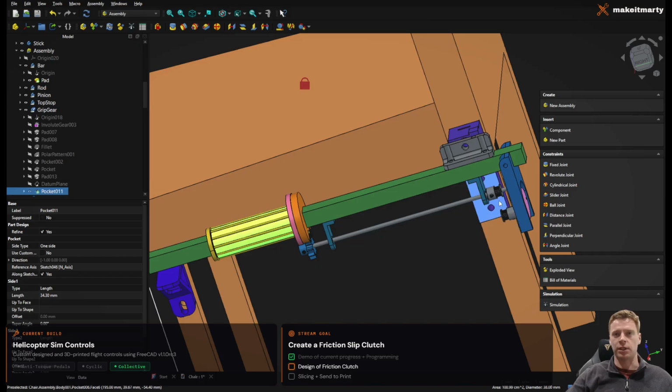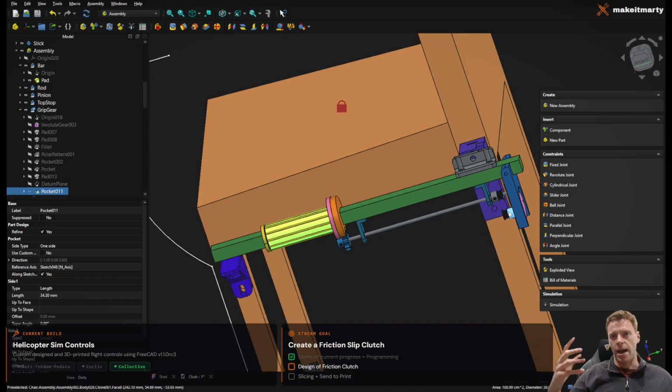But essentially you have this governor, which is a PID loop, and it's looking at the blade RPM and the engine RPM, making sure that the blade RPM, which should be constant, stays constant. It's changing the engine throttle to keep that blade RPM constant.